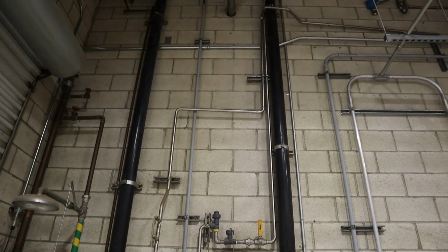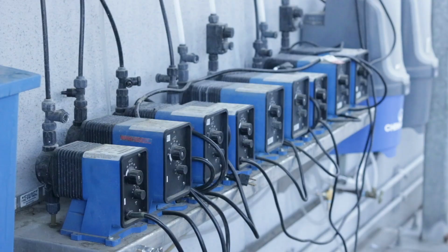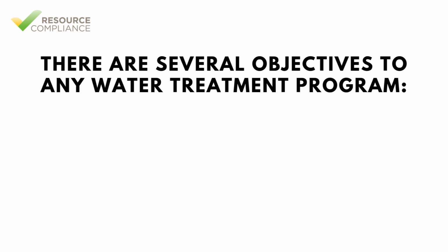Condensers use water as a heat transfer medium, which exposes the equipment to risks such as scaling, corrosion, fouling, and biological growth. Effective water treatment helps a refrigeration system to operate efficiently and reduce downtime. There are several objectives to any water treatment program.